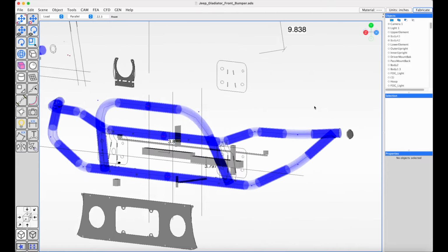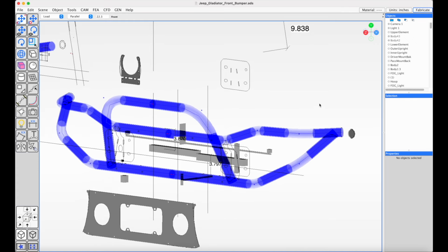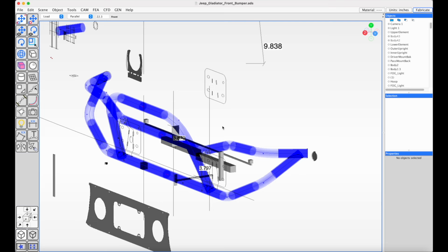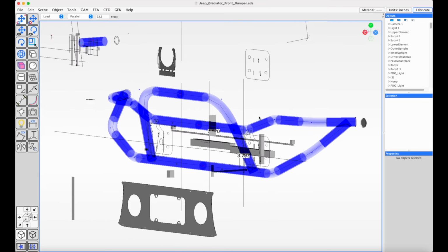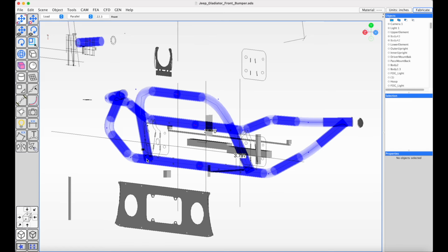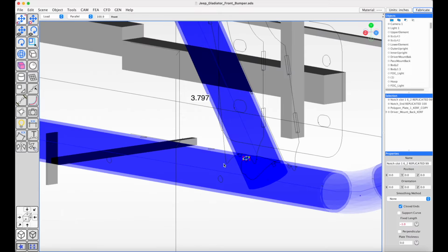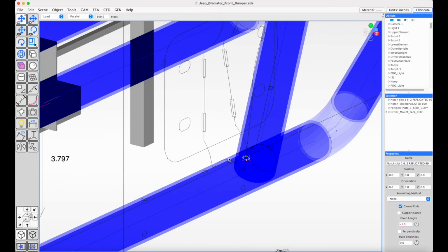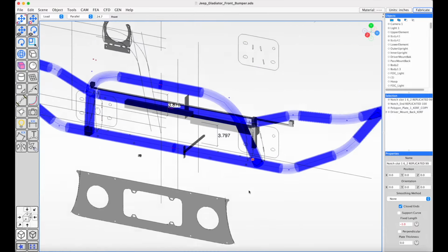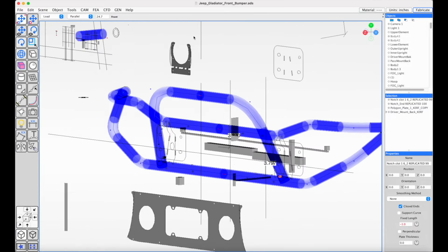And these parts can be cut in about 10 or 15 minutes and bent in also about 10 minutes or so, and then fit together on a jig that holds them in place. And the slots hold the ends, and this hoop in the lower bar, and we have plates, and then I can tack them together and weld.